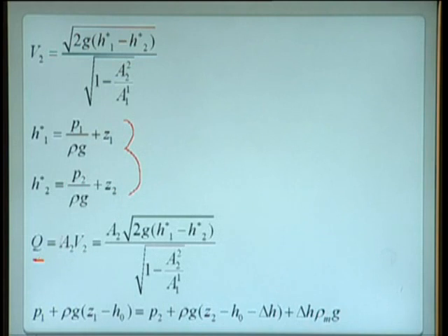Now, we know that discharge is equal to mass flow rate, without considering the mass. This is just flow rate Q. Flow rate is equal to area multiplied by velocity. So, generally for incompressible fluid we define the flow rate instead of mass flow rate. So, flow rate is equal to A2V2.